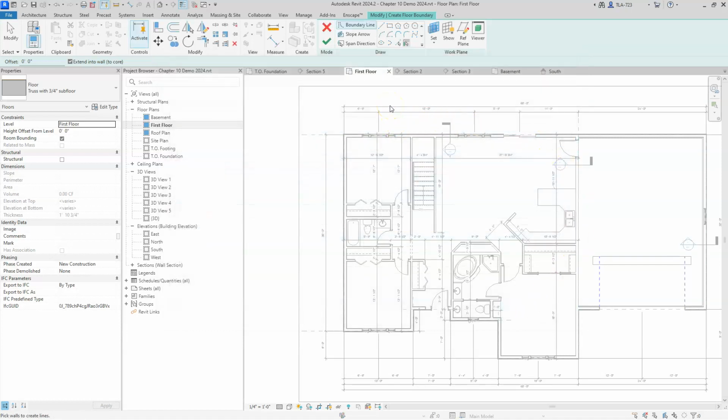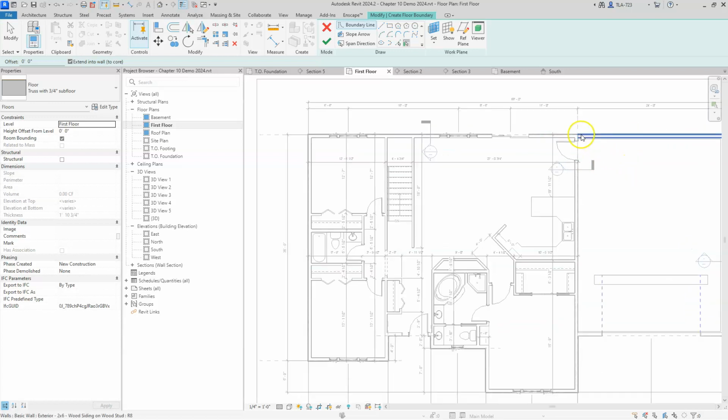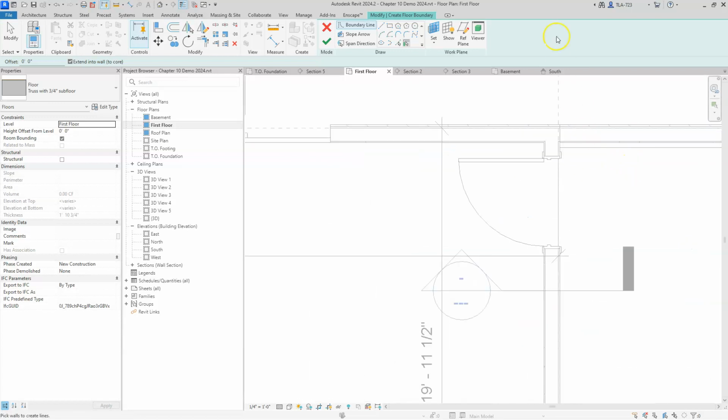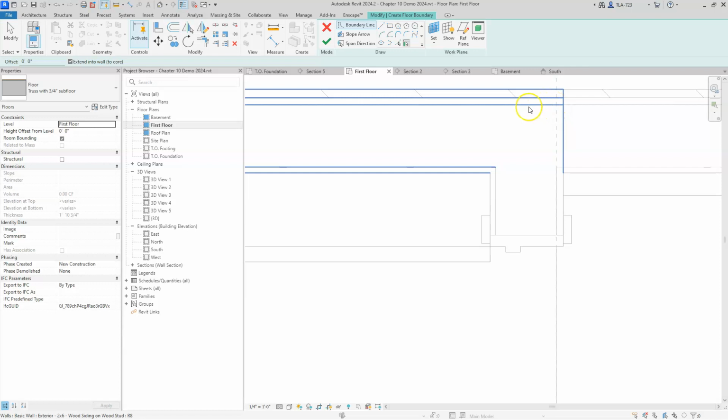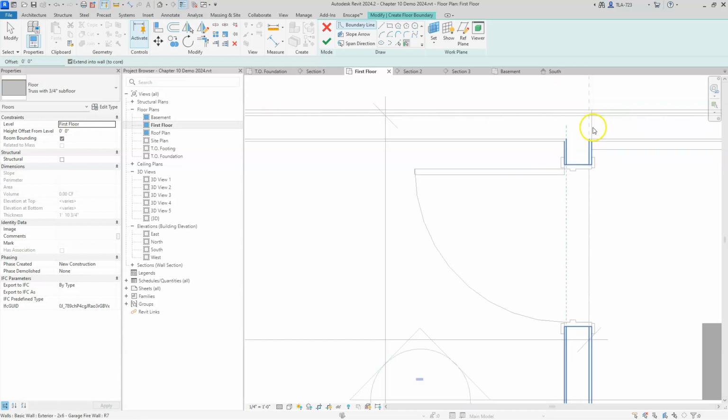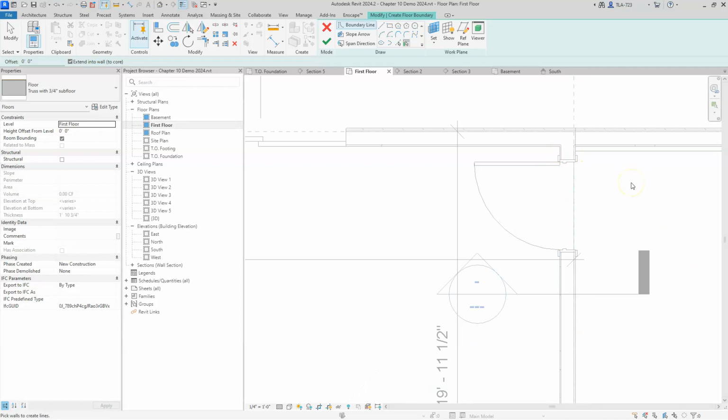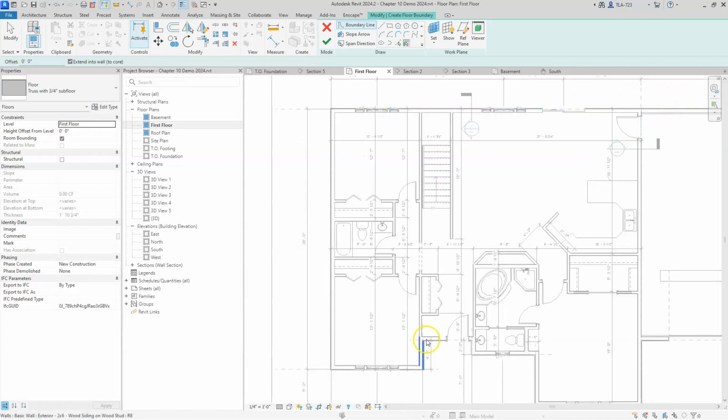And now we have to define the boundary. This does require just a little bit of thought. Remember that the boundary is typically going to follow where we place the reference planes, and those are typically aligned with the outside face of the stud wall and the concrete foundation wall. So as long as we follow that reference plane, we should be in good shape all the way around the perimeter of just this left part of the house, not the garage.